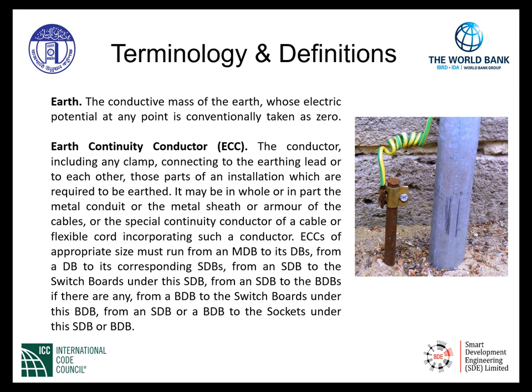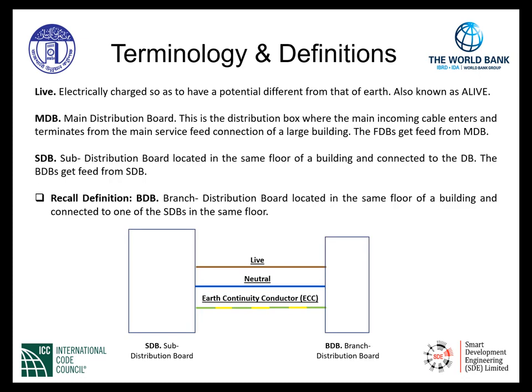This definition makes it clear the function and the routing of the earth continuity conductor. We will have many examples of this application coming up in this presentation and also in the electrical part 2 presentation as well. The term live is described as electrically charged so as to have a potential difference from that of Earth. It's also known as alive.